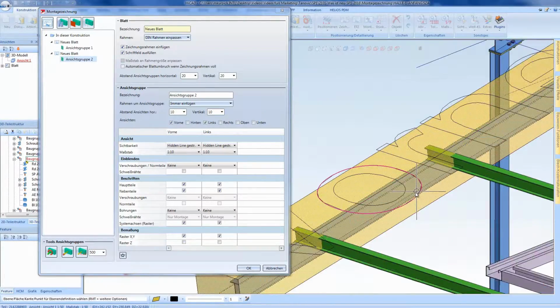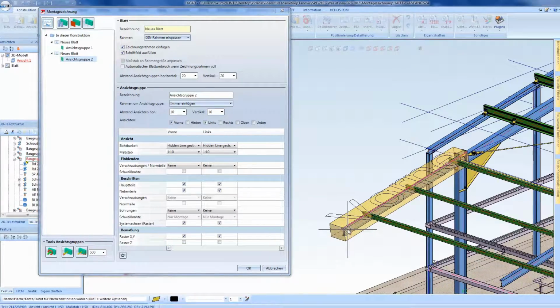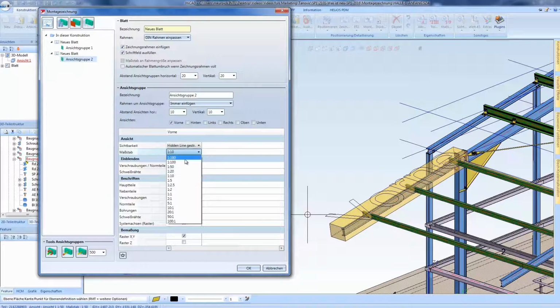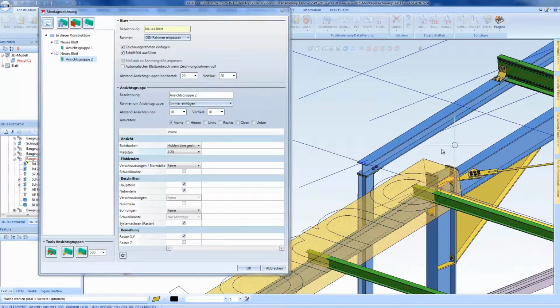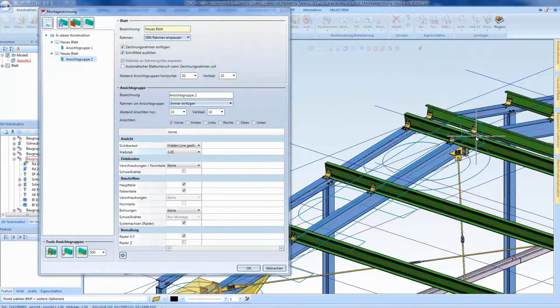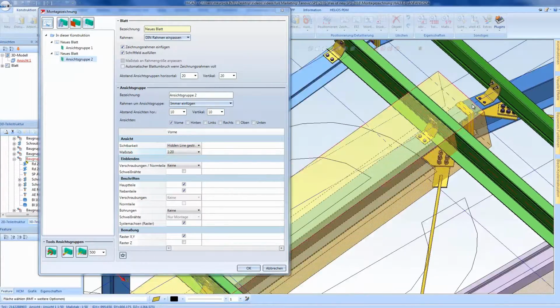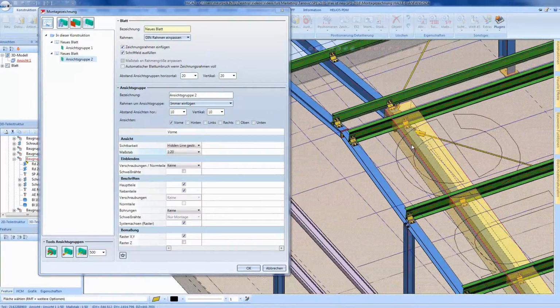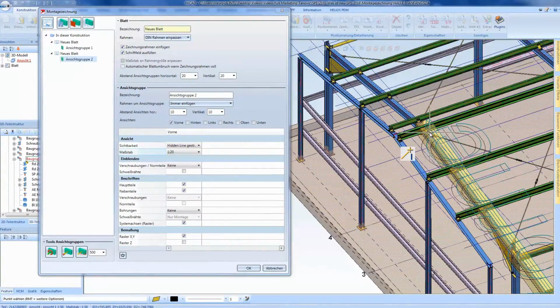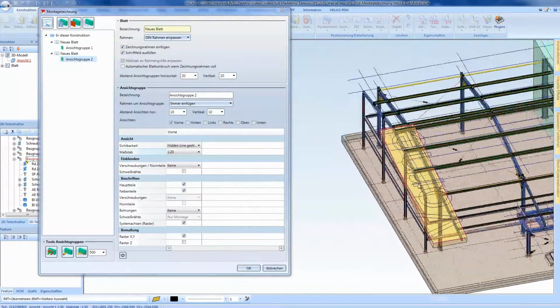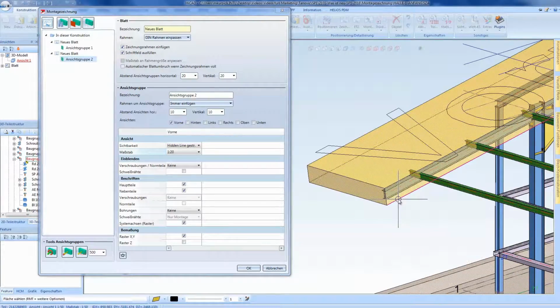In the next step we will create another sheet and define another view group. In this case we would use the selection via plane. We select the flange on this beam as the plane, and again the start box appears. Then we adjust the box in such a way that it includes all we want to see in the generated mounting drawing later. Here, again, we have the option to select the facet via 2 edges or an entire surface.